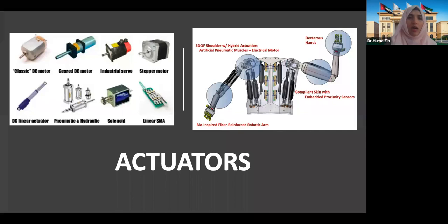These motors range from DC motors to servo motors to stepper motors. And obviously, there are different ranges within them. DC motors or gear motors are the ideal choice for robots with wheels or tracks, as they provide continuous motion or rotation.